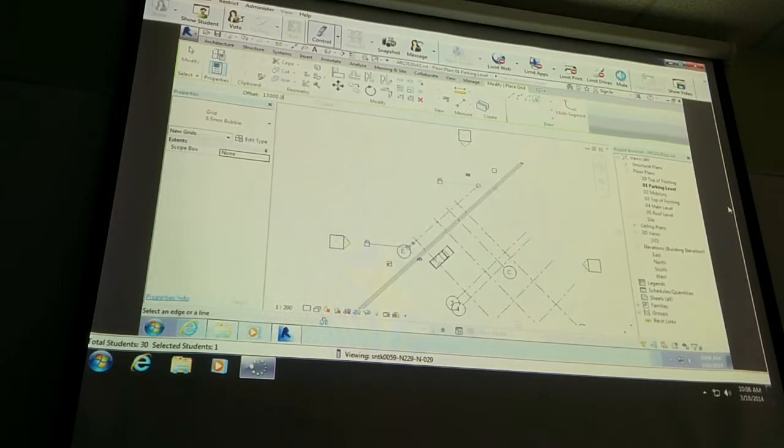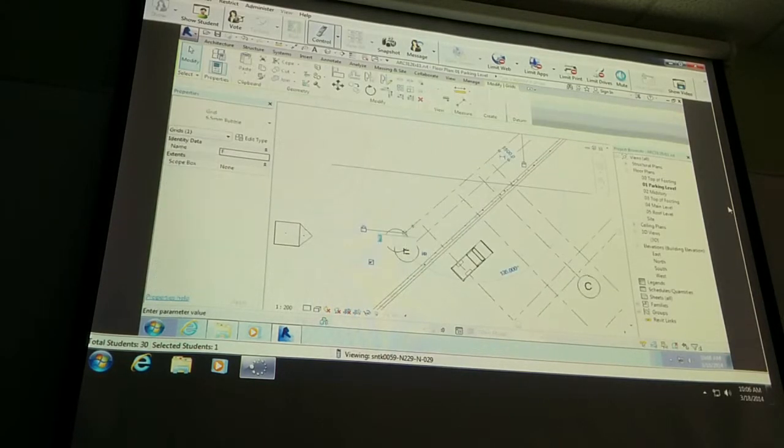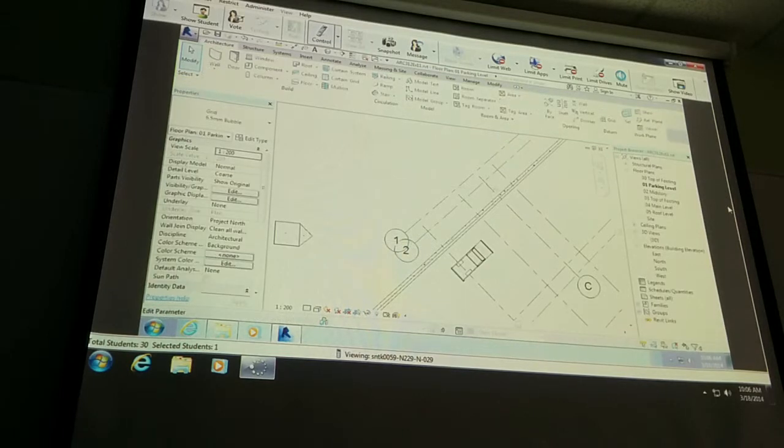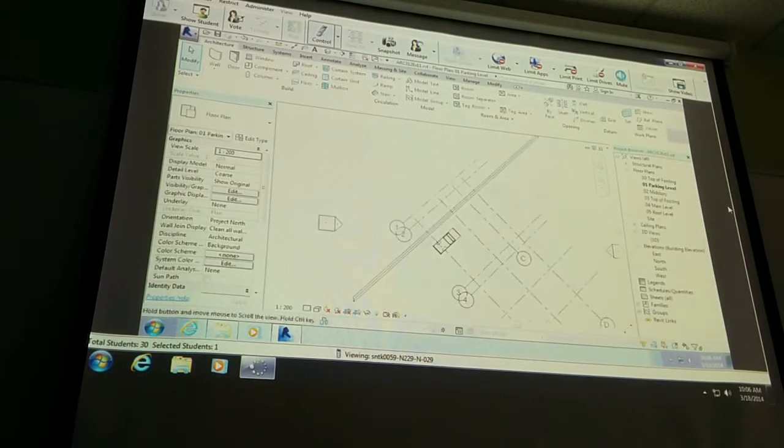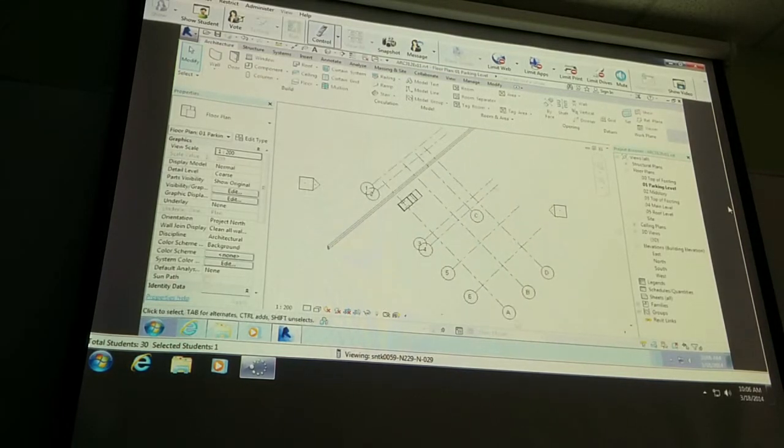And change your offset to 1500 and create grid line 1. Okay, that looks good. So we've got all of those. Now, position the other grid, since this grid here, of course, is at 45 degrees, the other grid isn't.